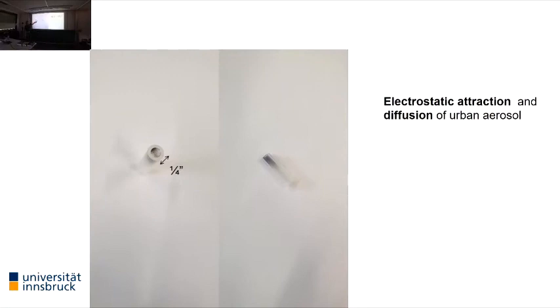And so for our CO2 and NOx measurements, we pull outside air through these lines. And what you see is in the first centimeter here, it's black, it's soot. So that's outside aerosol that's already deposited very close to the very beginning of our line. And this is a well-established effect. So if you measure aerosols in the outside air, you never use plastic or Teflon lines. And I should say we don't use these to measure aerosols. We use this just to measure gases, where the effect is less of a problem.